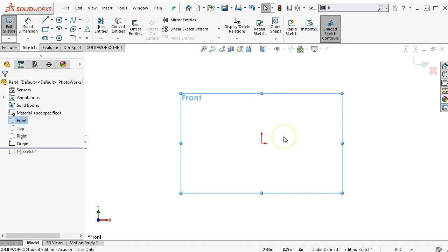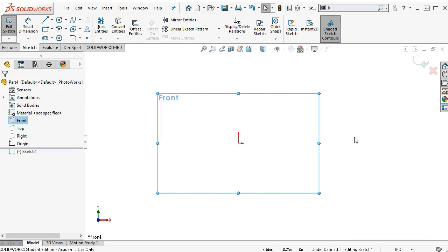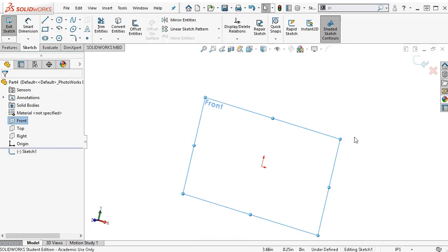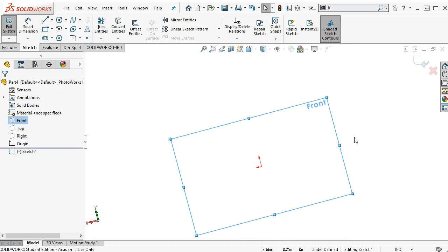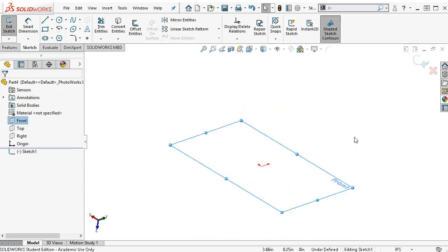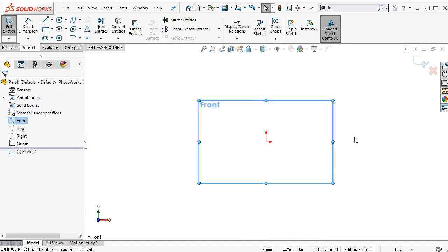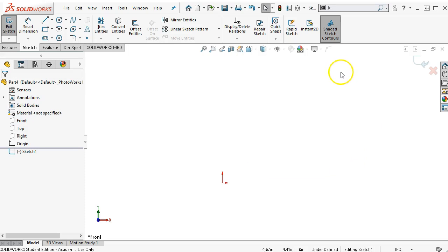Red origin, and I think I've mentioned this in previous videos, but I'll bring it up again: the long leg is vertical and the short leg is horizontal. So those arrow keys, if I hold down the control button, we are panning around on the screen, and if I hold down the alt button, then we're rotating 90 degrees, and if we are just doing arrows, then this is rotating in the 3D space kind of around the origin as we go through. And we can always go back to Control 1 or whichever view is going to put us back into the view. So get familiar with those keyboard shortcuts.